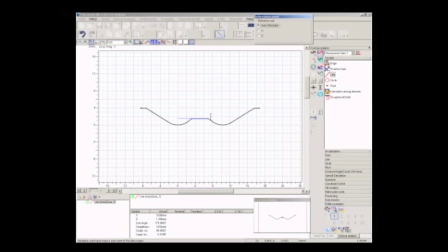Once I do, it drops the line in, and then I can come back over to my tools, rotate to the x-axis and click on that, and that levels it. Now, it wasn't out of level to the instrument very much. But if it had been, it simply would have rotated and brought it back in level. That's right. And you can see down here, we're building a list of features that we're creating, which is the other part of our part program.